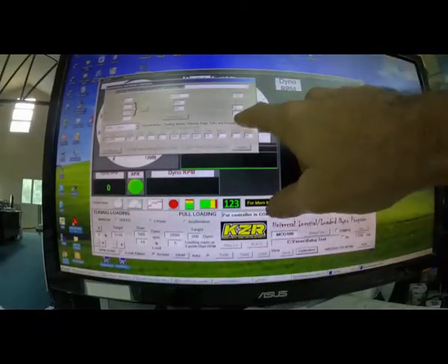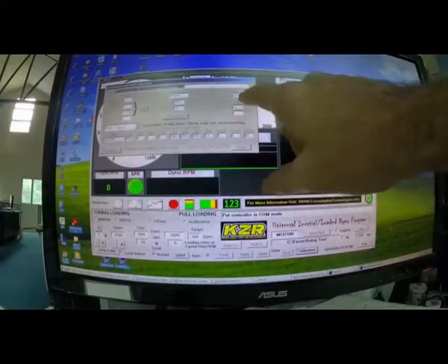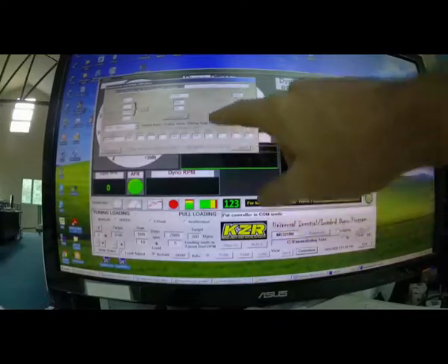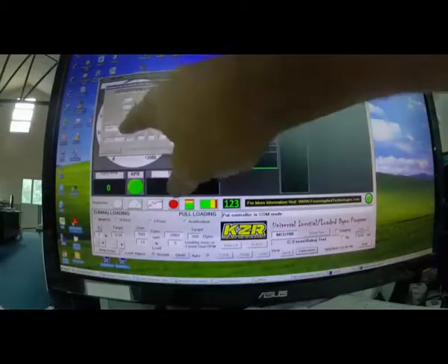Typically, that's quite a small number, 0.01 or something like that. And you include the gear ratio, and then it shows you how much your equivalent engine inertia is compared to your dyno inertia. Maximum RPM and maximum torque, a couple of the typical parameters. Also, we can automatically calibrate friction.